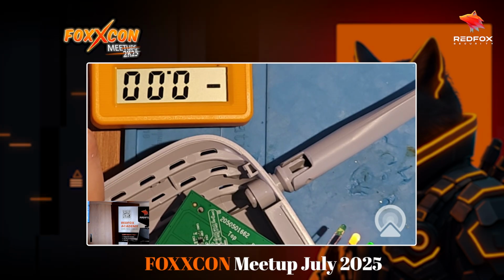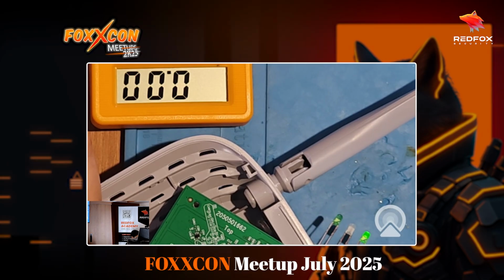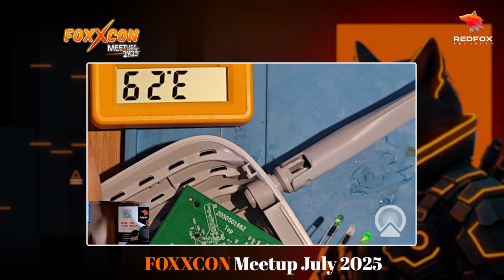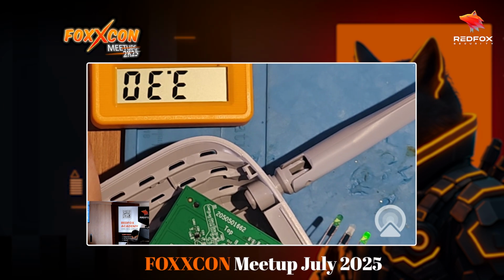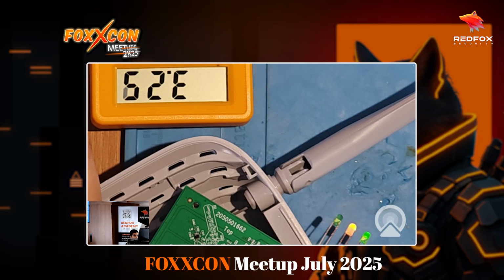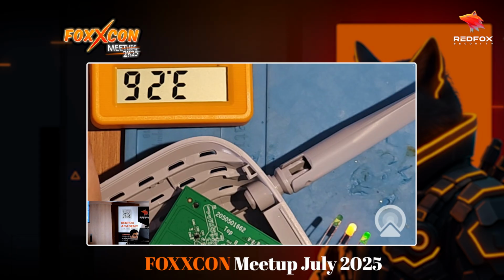So one end on ground and the other one on the first pad. You see 3.3 volts flashes directly. That's pretty much sure that that's the one that we're looking for. That's VCC. If we try any other port, then it shows 0. See, this is fluctuating. It is not really the one that we are looking for right now.